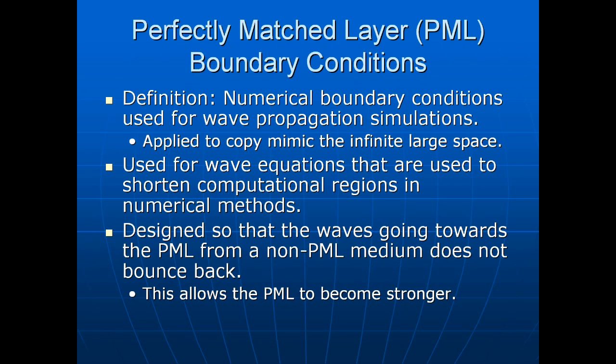The PML is constructed such that there is no loss in the direction of the interface. There are two conditions in order to form a PML. First, the impedance going from the background medium to the PML must be constant. Therefore, the impedance has to equal 1. Second, the direction perpendicular to the boundary has to have a dielectric and permeability that is inverse to those in the other directions.